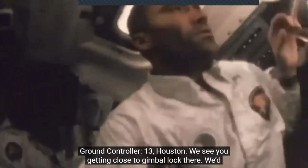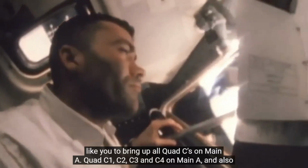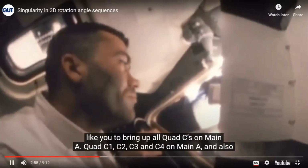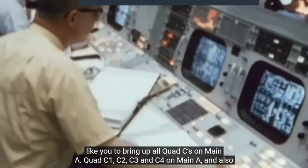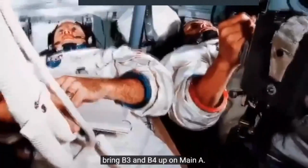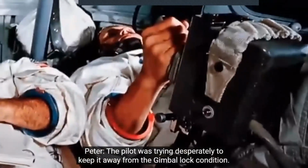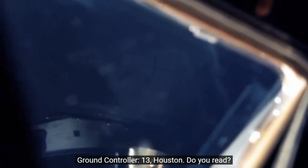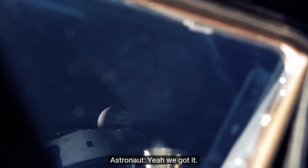13 Houston, we see you getting close to gimbal lock there. We'd like you to bring up all quad C's on main A, quad C1, C2, C3, C4 on main A, and also bring B3 and B4 up on main A. The pilot was trying desperately to keep it away from the gimbal lock condition. 13 Houston, you read? Yeah, we got it. Over. Okay, can you tell us anything about the venting?